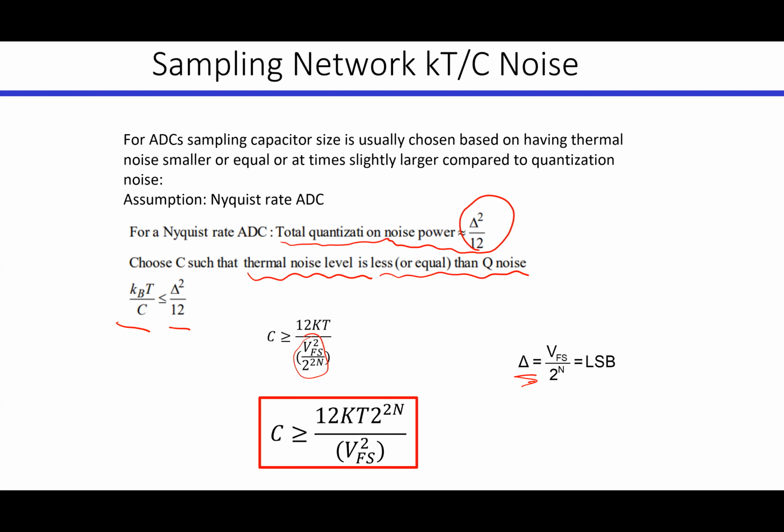So you need to make sure that you are not dominated by the thermal noise, and make a proper choice of your sampling capacitor. But isn't quantization noise also detrimental, or is it because we are working in higher resolution that it's not very large so that it can mess up our circuit? What do you mean by that?